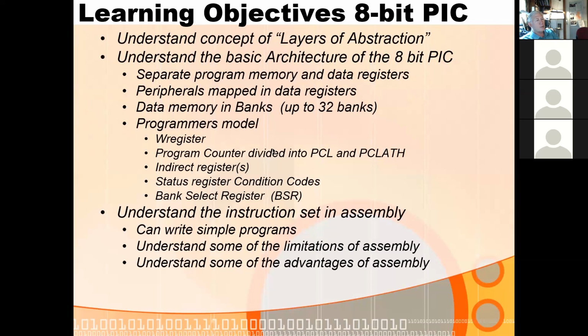Now, because even in this chip, we have pipelining, it's actually pointing a couple of instructions ahead, so that when you get a branch, you have to flush out the pipeline and reset the program counter to point to the right instruction, and then away you go. So anytime you take a branch on this chip, you burn one instruction cycle. You just waste it. So the more branches you take, the more instruction cycles you're burning, but the more efficient use you're making typically of your program memory. That program counter is automatically incremented to point to the next instruction every time it fetches the current instruction.